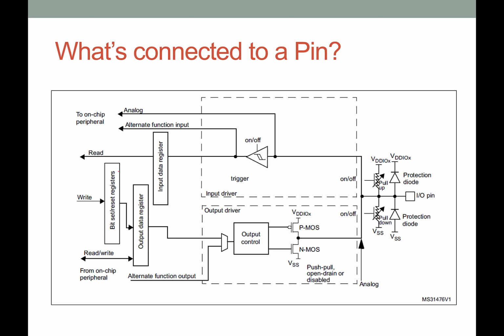Okay, we've already talked about this, what's connected to a pin and so forth, but notice here is the mode that we're taking for that GPIO pin. We're taking it as an input in here, and we're taking it as an analog input. So that means it's not going to go through this hysteresis curve, we're not going to do any alternate functions, and we're obviously not treating it as a binary bit or anything like that.